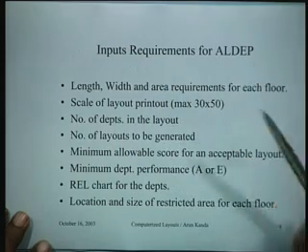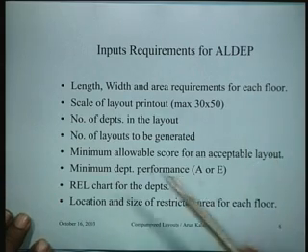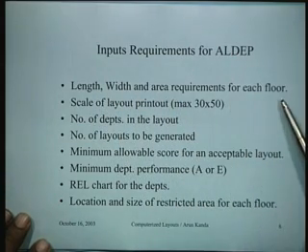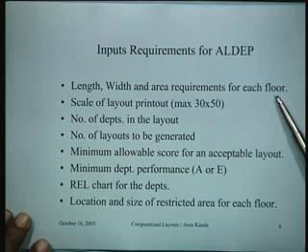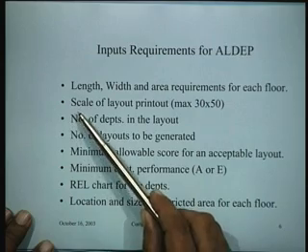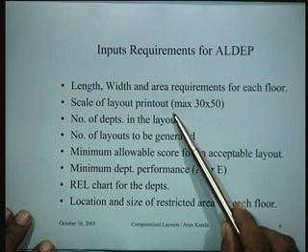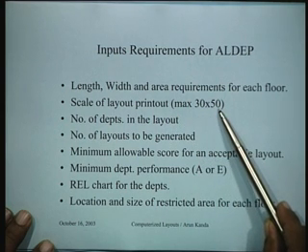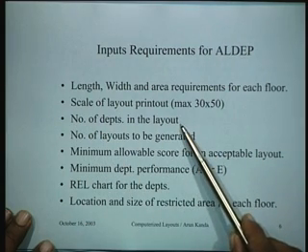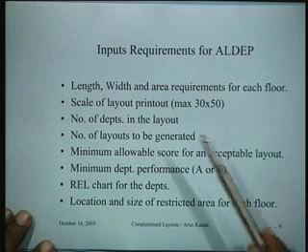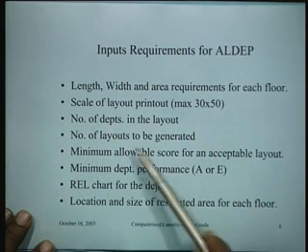So here are the input requirements for LDAP. What is the input needed? You need the length, width and area requirement for each floor on which you are going to do the layout. As I indicated to you, LDAP has a provision for handling layout problems on 3 floors. So you have to specify this information. You need to specify the scale of layout printout, which is generally a maximum of 30 by 50. You have to specify the number of departments in the layout. You have to talk about the number of layouts to be generated.